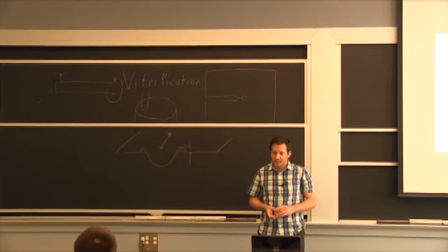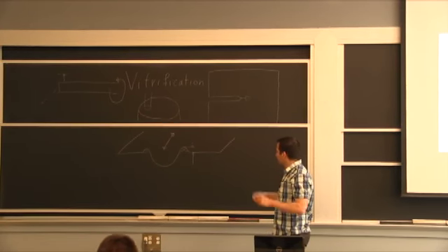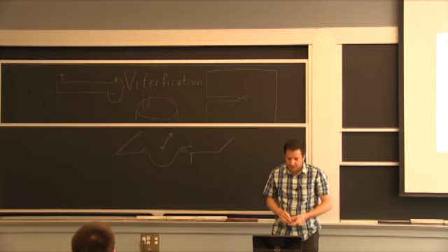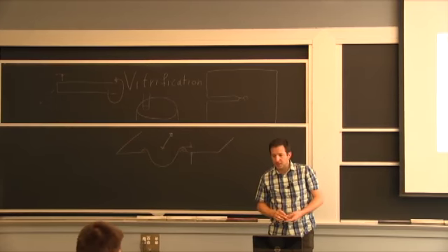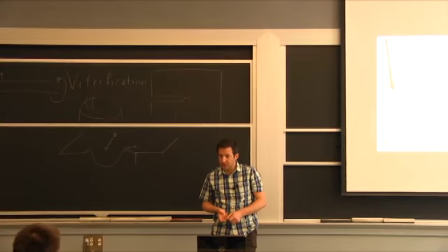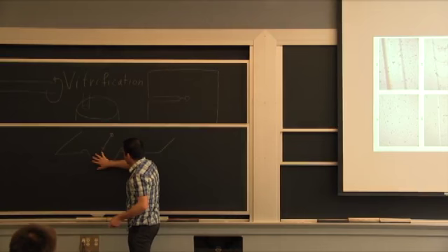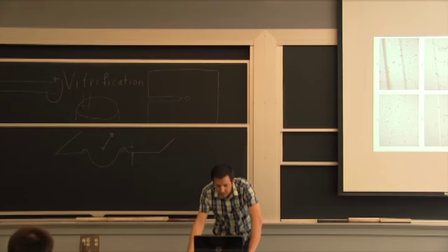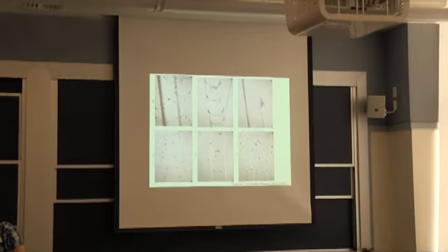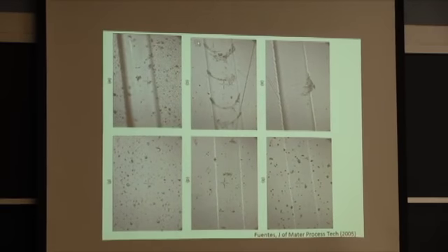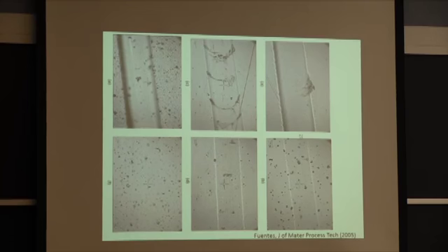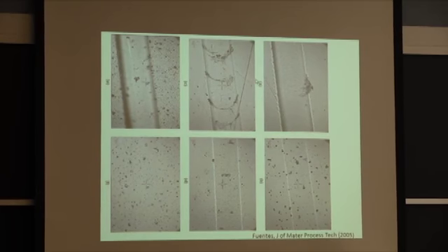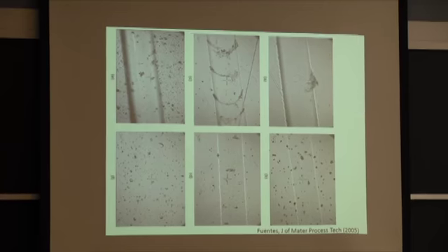So in this type of ductile wear, where you have permanent deformation, your design becomes more oriented towards strain hardening, but also fracture toughness. Because when you make this deformation, you end up with a lot of residual stresses. And that's what this image shows here, where you form these cracks that are running across the scratch here. So a scratch was running this way, and you have these hairline cracks forming in the other direction. Eventually you can have particles falling apart in a brittle manner.